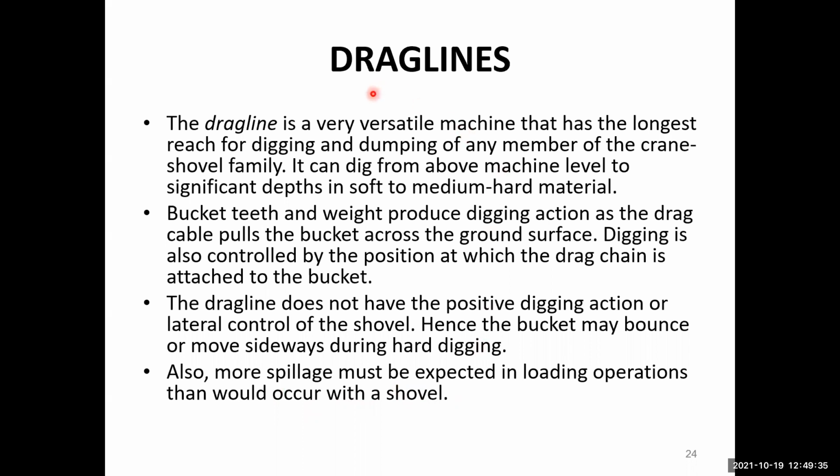So dragline is another excavating material equipment. Its use is also there in those situations when we need a longer reach, and where the normal hydraulic excavators or the shovels may not provide us the desired operations because the approach of the material is not that convenient. But their disadvantage is that the draglines can only drag the buckets towards the machine.